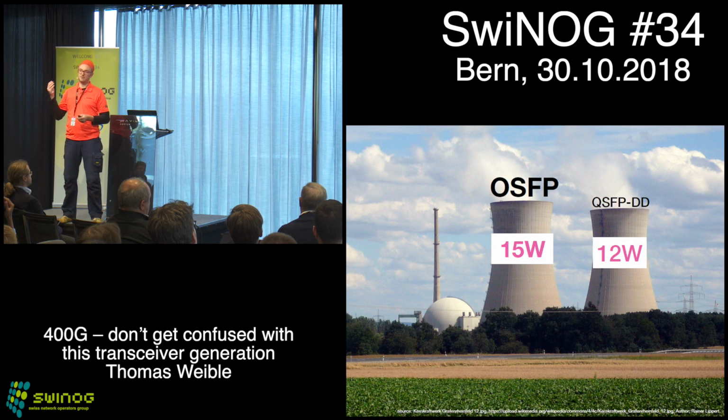We get in there 15 watts of electrical power, and even more critical, we are able to get 15 watts of thermal dissipation out of that transceiver. For the QSFP-DD, it's slightly less, 12 watts currently. But the goal is to make them equal, getting up to 15 watts, and I have seen some lab environments where they even try to get up to 20 watts.